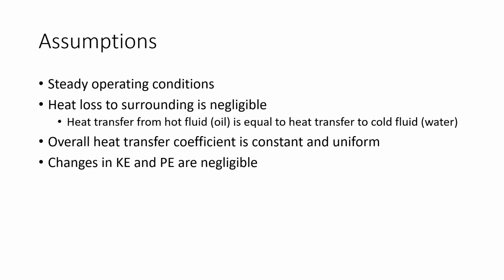First, we need to start with a couple of assumptions. This is steady operating conditions for this system. Heat loss to the surroundings is negligible. The heat transfer from the hot fluid is equal to the heat transfer of the cold fluid. The overall heat transfer coefficient is constant and uniform, and the changes in kinetic energy and potential energy are negligible.